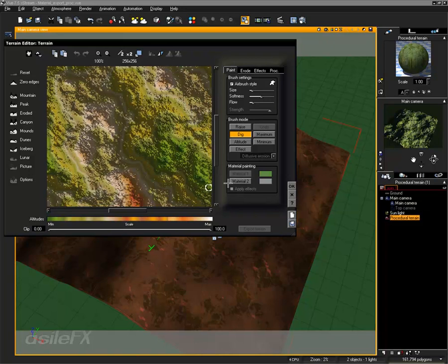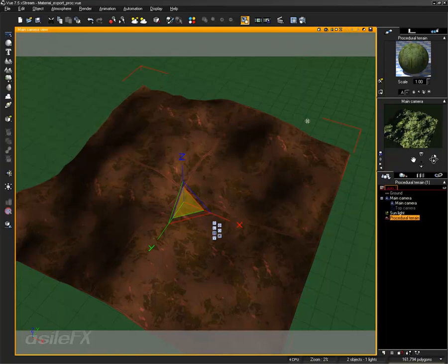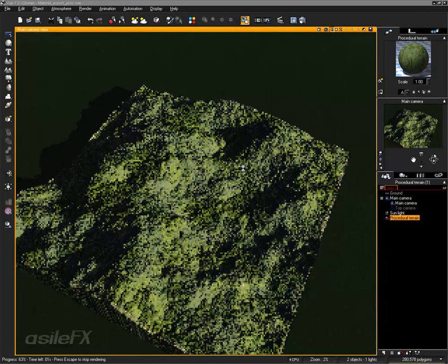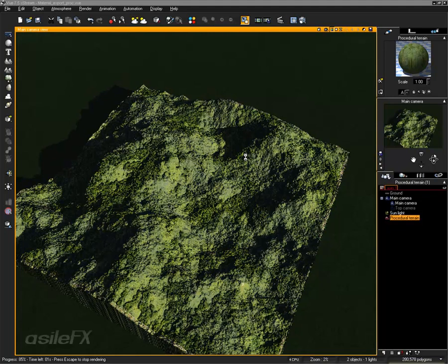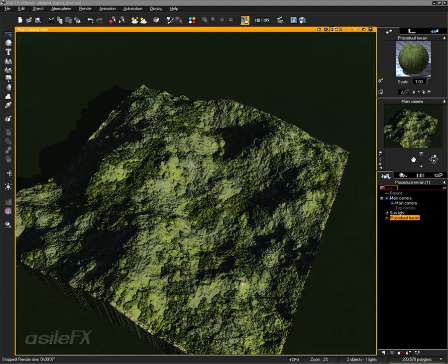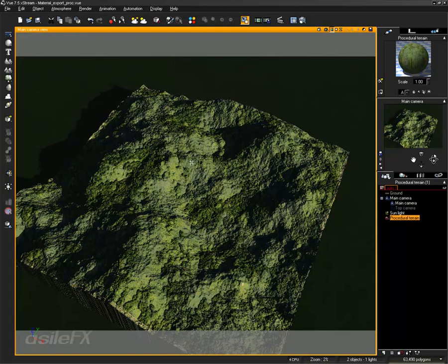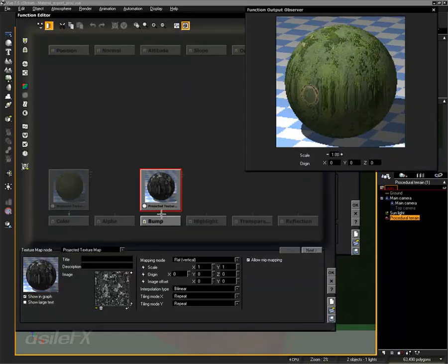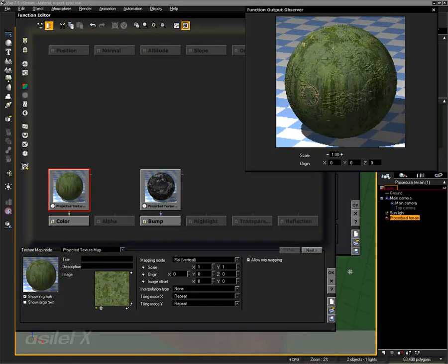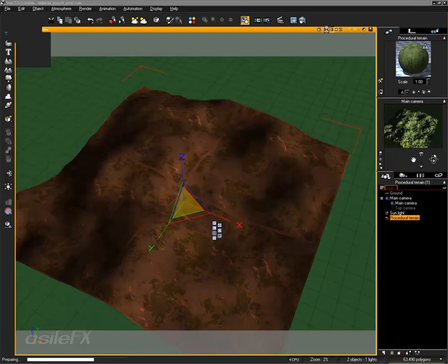And because of the way this material was created, it might be difficult to tell whether or not the map is showing up correctly, but it looks like it is a little bit off because we did have that forest material, which is the bumpy darker green, showing up on flatter surfaces, and it doesn't look like it's matching correctly. So one thing I'm going to try to do is first switch our mapping mode in the material to automatic. And if that doesn't work, we'll just need to modify the material manually.